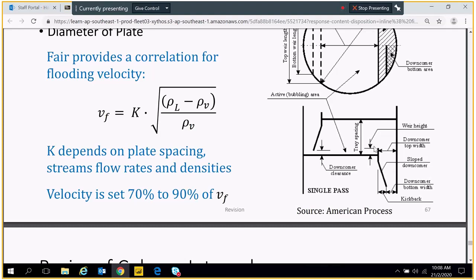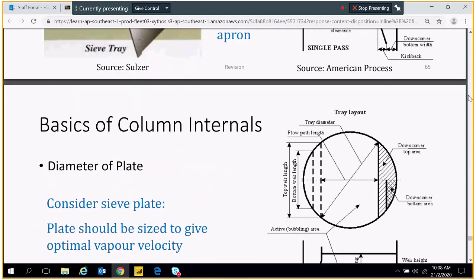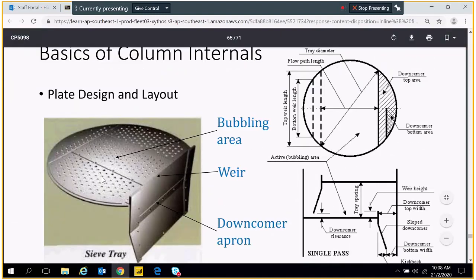Or rather, you have normal liquid, but your vapor velocity is too low. What happened to the liquid? Liquid looks for opportunity to go through the hole, drop by drop. This is called weeping, because vapor velocity is too low. Liquid passes through a hole.